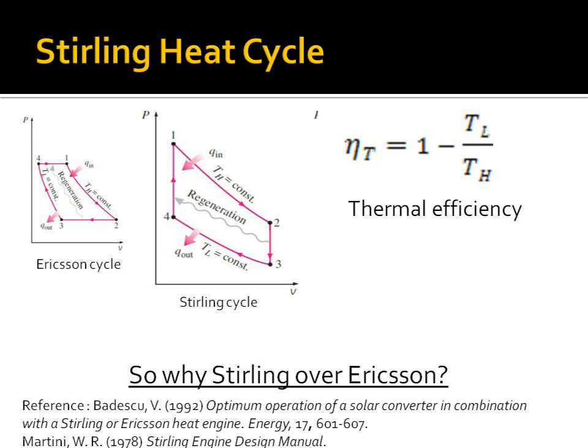Well, through my research, the Ericsson cycle has a larger power-to-weight ratio compared to the Stirling engine. However, the Stirling engine has a large, diverse range of power output in that it can go down to milliwatts. The Stirling engine can produce low power with a small-scale volume. The Ericsson cycle can produce that same power, but the volume needs to be greater. So for those reasons, the Stirling has better small-scale potential.